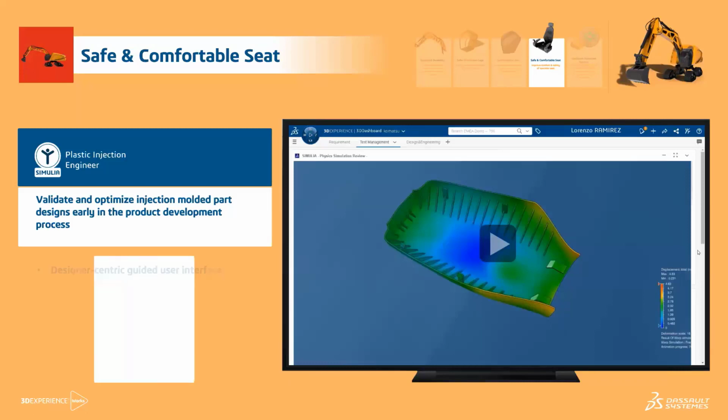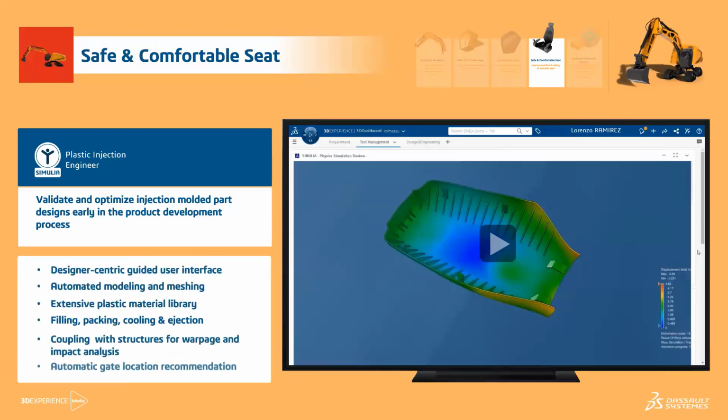So the plastic injection engineer, this type of solution, allows you to estimate the filling of the cavity, which is very important for this type of tool. What matters for the plastic injection tool is the database, because the material data is very complex to get if you're a user. So only, let's say, the laboratory can provide you this type of material data. Even sometimes, the plastic manufacturer doesn't have all the filling data to perform this simulation. So you have to go through a laboratory to estimate the different viscosities you can get as a function of the temperature.